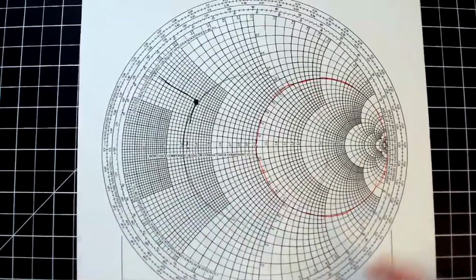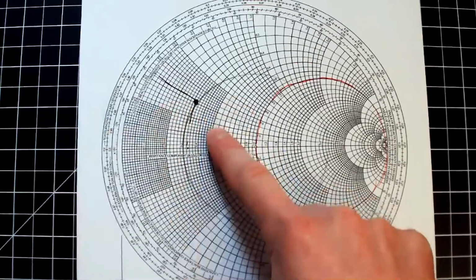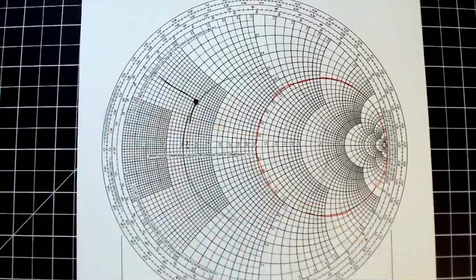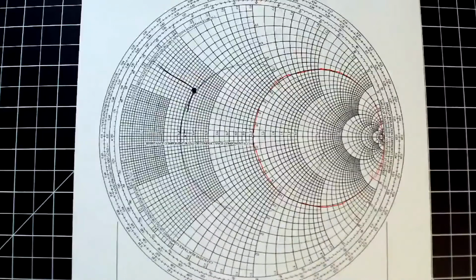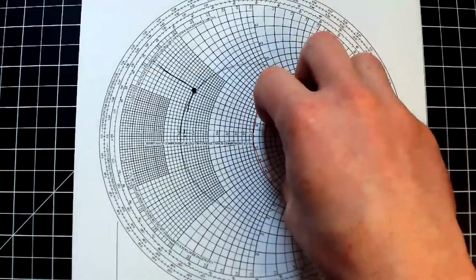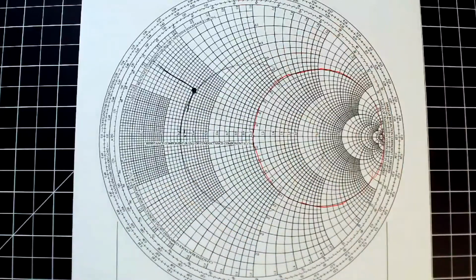So when you plot your normalized impedance, you have to read off the impedance circles and then the reactances. You don't treat it as a complex number and plot it with a magnitude and a phase. That kind of makes sense? Is that where that confusion came from? That's exactly where that confusion came from. Okay, we are not inside the circle. So those are two completely separate ways to get the same dot.